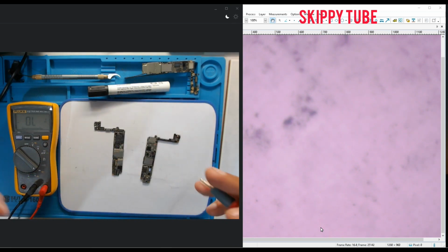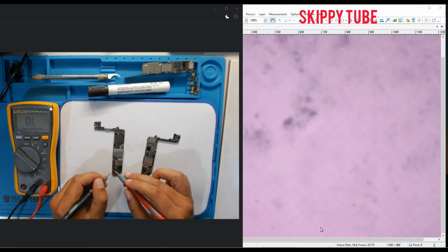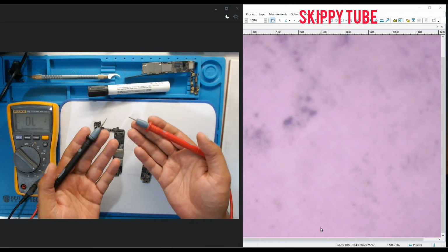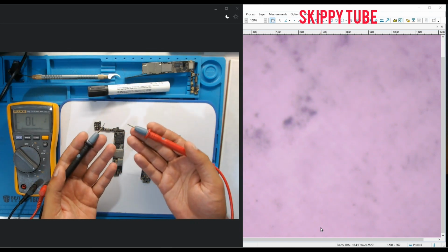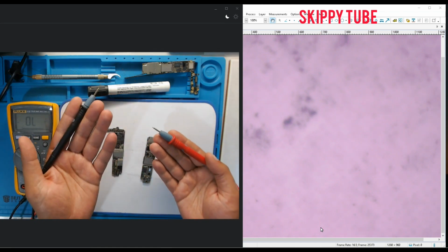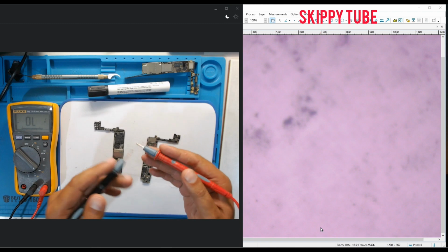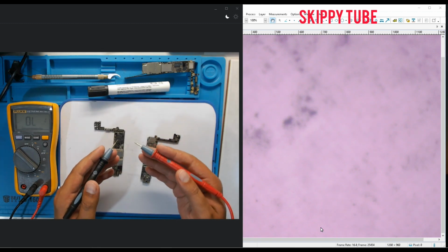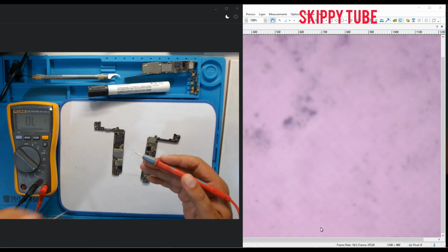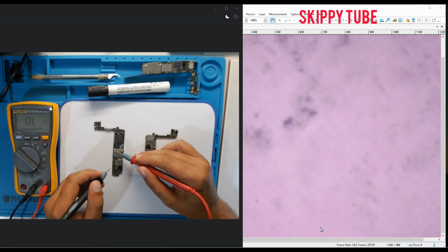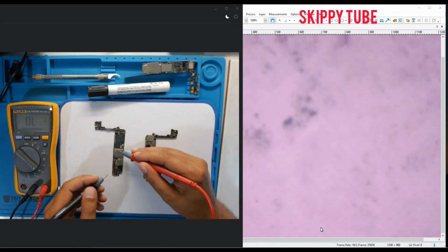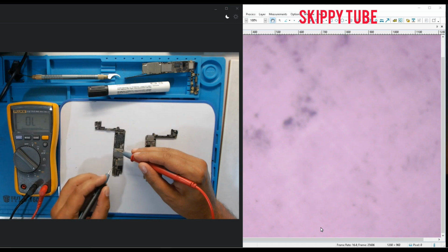First we want to check the battery connector diode value. I told you diode value; every technician with experience knows this: red is the positive side and black cable is the negative side. To check the diode value and find the diode value average, we need to put the red cable on the earth or ground, and the black cable is connected to this one.